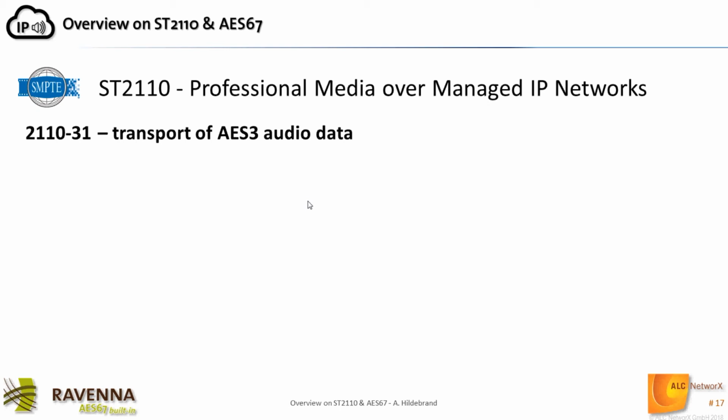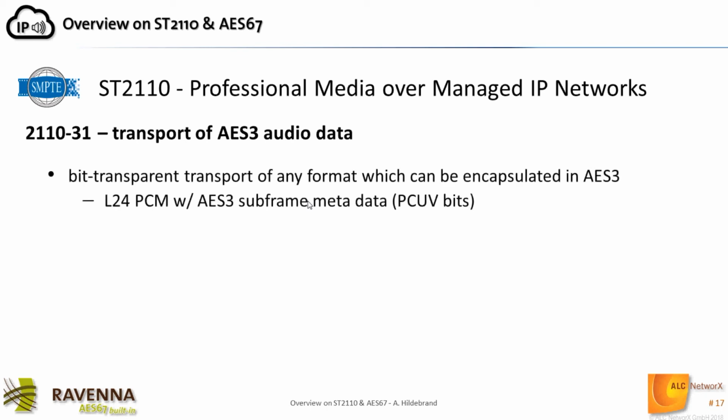And so SMPTE came up with the -31 document. And the -31 document covers the transport of AES3 audio data. So that can transport any 24-bit PCM signal with the corresponding AES3 subframe metadata, the so-called PCUV bits.